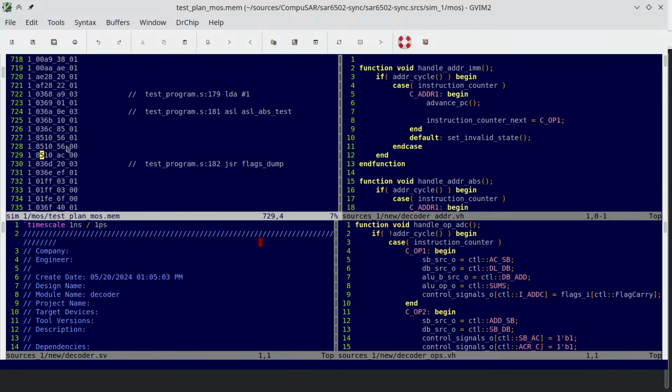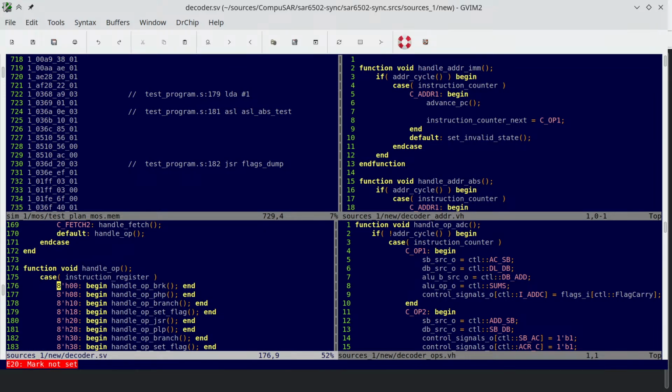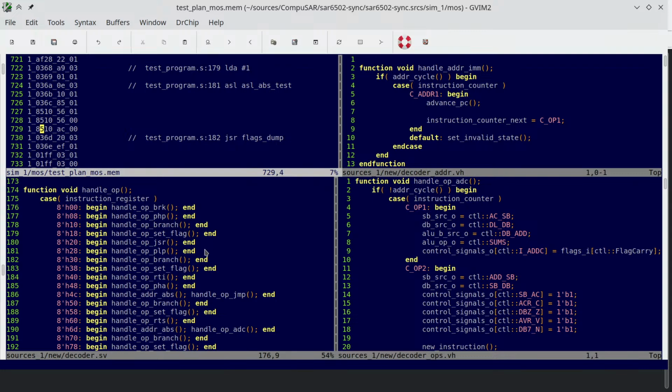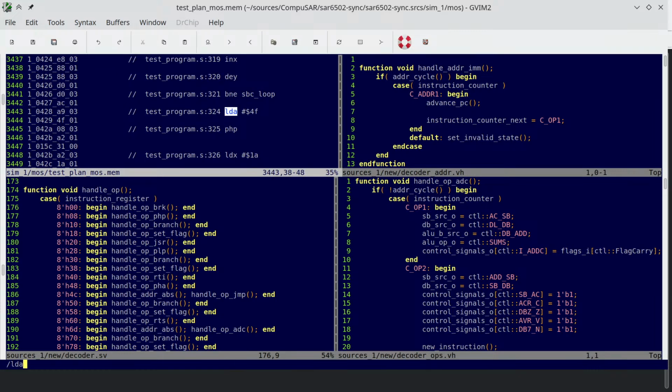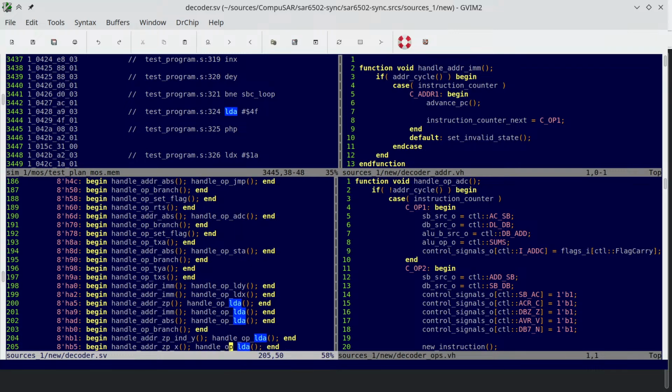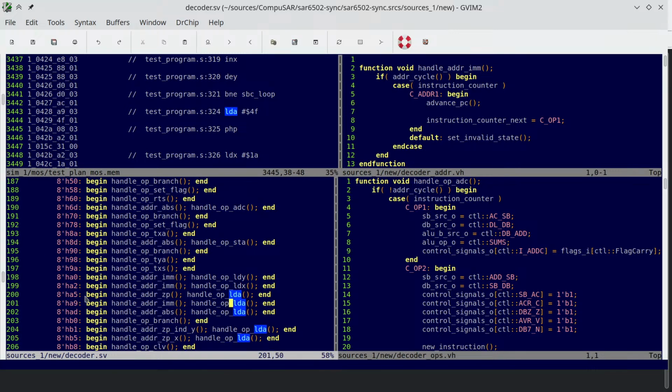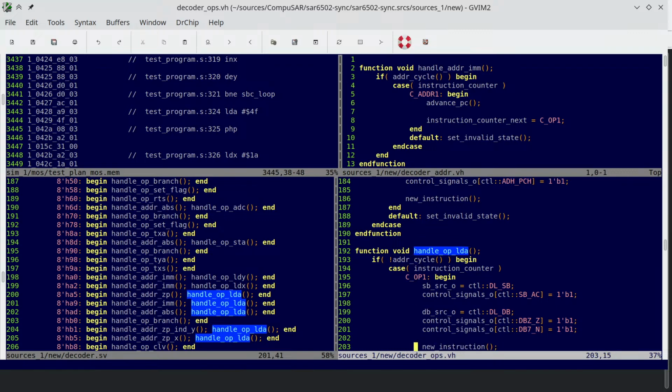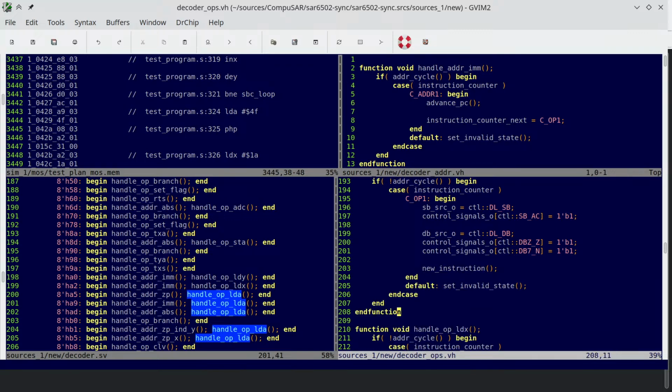If we look at the code we had so far, and we look at the case that defines the opcode, and then we look at the different load A instructions, we see that the difference between the different opcodes is with the addressing modes, and the opcode itself is typically just a single cycle, or at most 2 cycles.